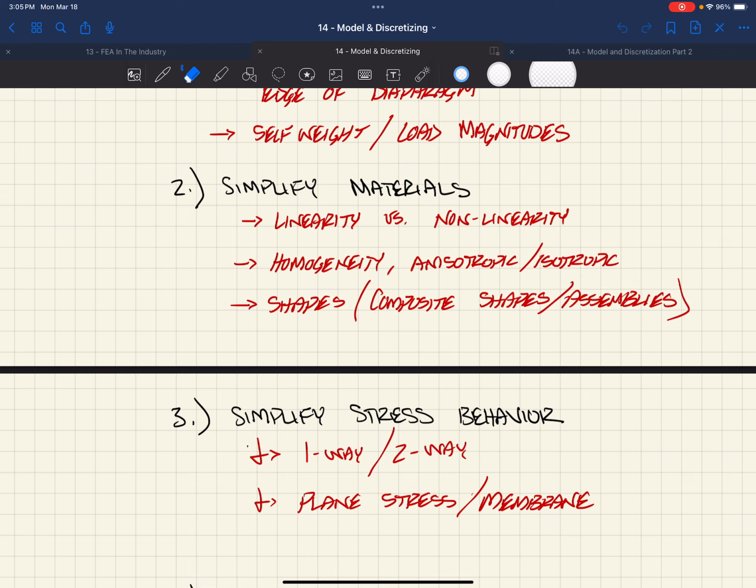Maybe you are going to be very specific as to how to model things. Maybe if you are doing glazing in a big high-rise building, you'd want to have those specific cross sections in VA. In other instances, maybe you just are curious into the stiffness, because I'm not really worried about the intricate micro scale of what's going on where a mullion in a window hits a cross mullion in a window or a sill in a window. We're really worried about, well, after the wind hits this whole curtain wall, how is it going to distribute that load? Well, it's going to distribute it based on stiffness, so I'm just worried about the cross-sectional properties.